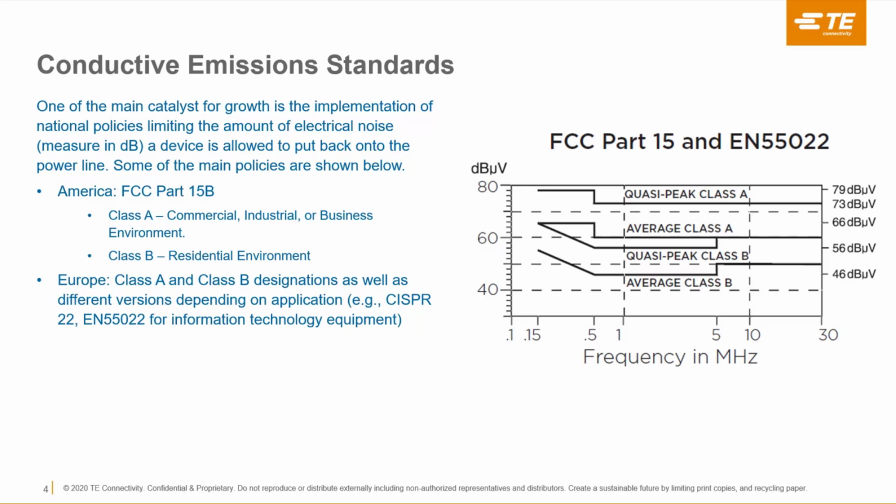That's the base of it, basically. Like I said, a lot of times our customers aren't really sure how much noise their product has until they're ready to go to testing, so we seem to always be a band-aid or a solution to their problem. If they really knew it was there, they'd be trying to solve their noise issue as effectively as they can, and not trying to deal with it right at the power line, where they're dealing with the full amount of current their product might draw, be it 5 amps, 10 amps, whatever. If you found out where your noise truly was and were able to suppress it, it would never get back onto the power line.